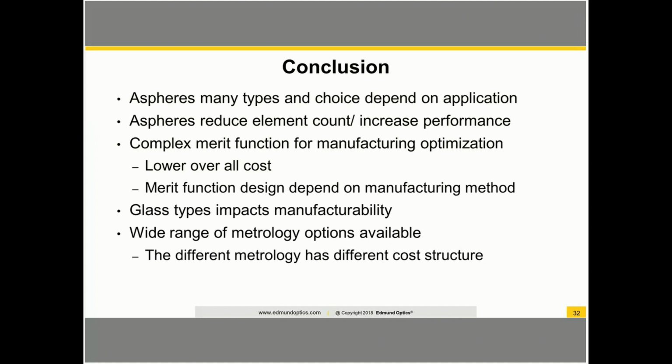Thank you. So the second question that we have is on a different topic, it has to do with molding, which is in Oleg's court here. What is the aspheric profile accuracy that can be achieved with molding? Is it better or worse than polished Aspheres? So what is the limit? That is a very short question, therefore I'd be more than happy to address it. We have a number of molded Aspheres in our catalog, and on the best side of performance, irregularity would be reaching somewhere between a wavelength and half of the wavelength. So that would be the answer to this question.